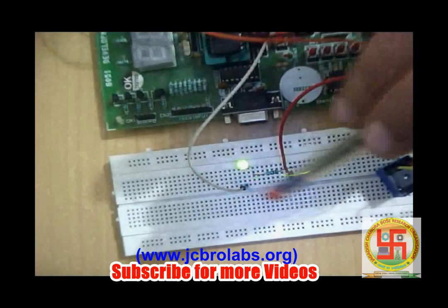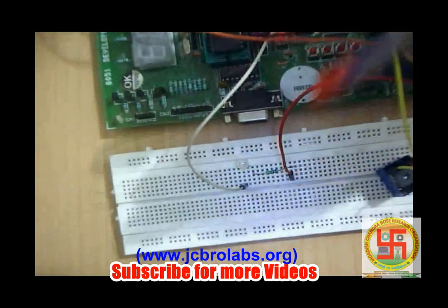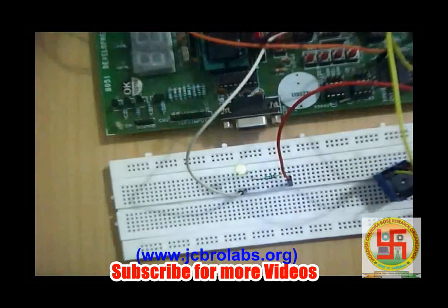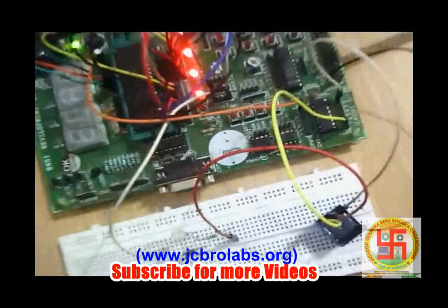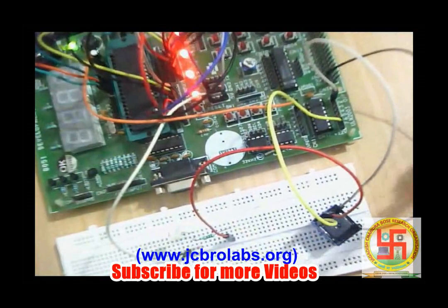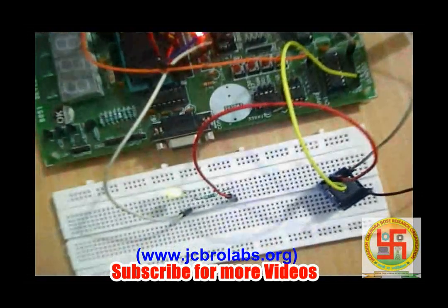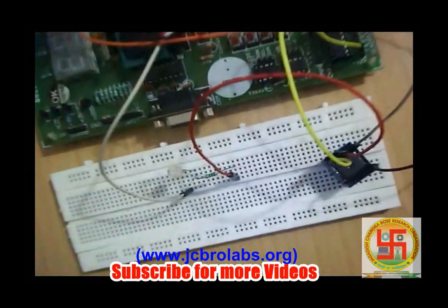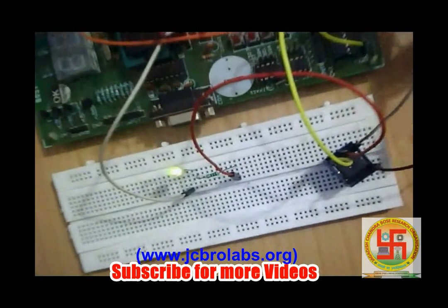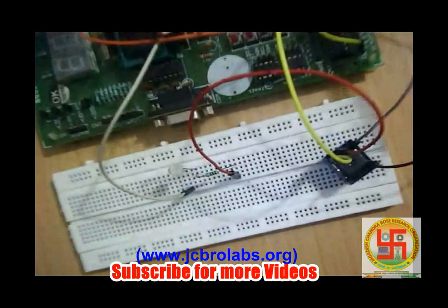It is connected through a 1 kilo ohm resistance, and one point of this LED is going to +5 and another end is going to the relay circuit, and the other end of the relay is connected to the ground, so that when the relay is on, it completes the circuit from VCC to ground, and the LED turns on. All these circuits are made as discussed in the circuit diagram. As soon as the relay is on, you can hear the tick sound. The LED turns on, and when the relay is off, the LED is off.